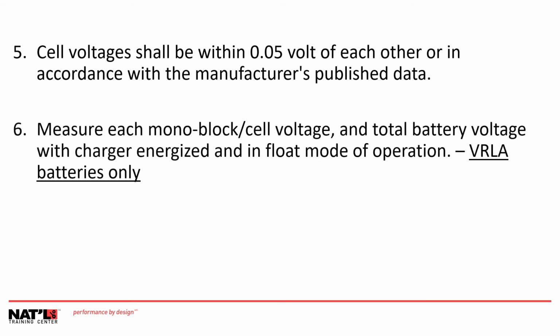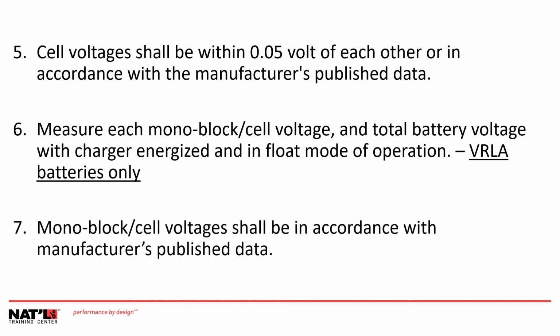Measure each monoblock/cell voltage and total battery voltage with the charger energized and in the float mode of operation. This applies to valve-regulated lead-acid, or VRLA, batteries only. Monoblock/cell voltages shall be in accordance with the manufacturer's published data.